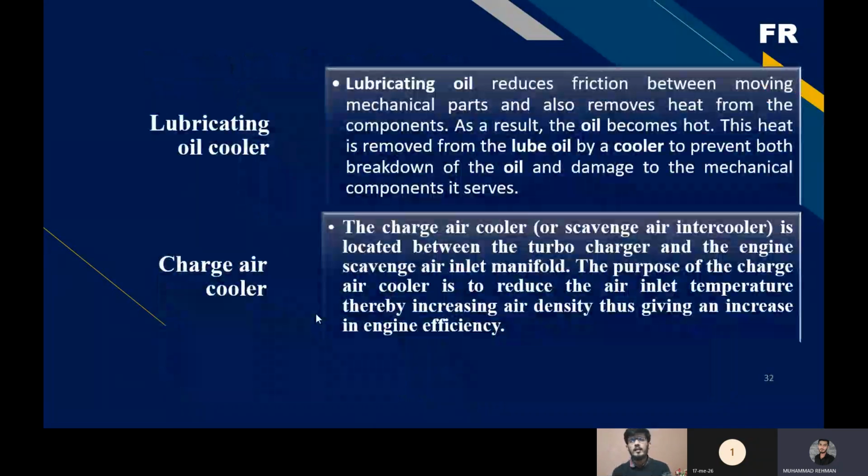Now, the lubricating oil cooler. We also use lubricating oil for cooling, to reduce the friction between the moving mechanical parts and also extract some heat from the components. As a result, the oil becomes hot, and this heat is removed from the lube oil by the cooler to prevent both the breakdown of the oil and damage to the mechanical parts. The second one is the charge air cooler.